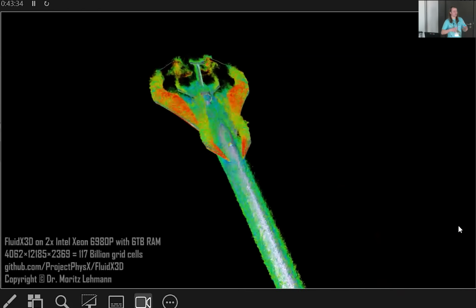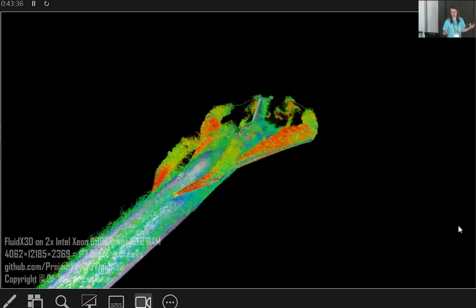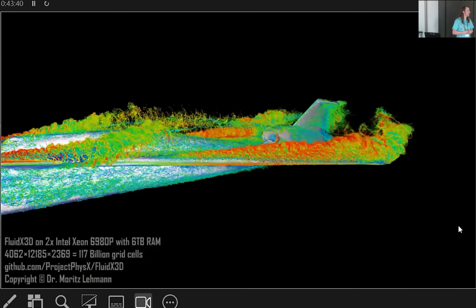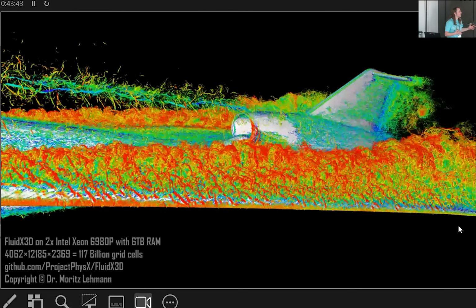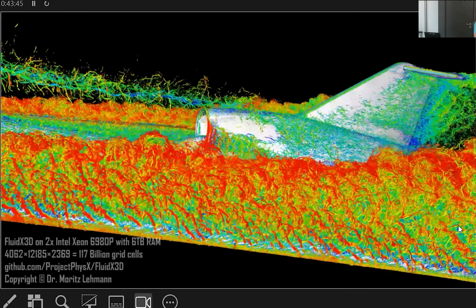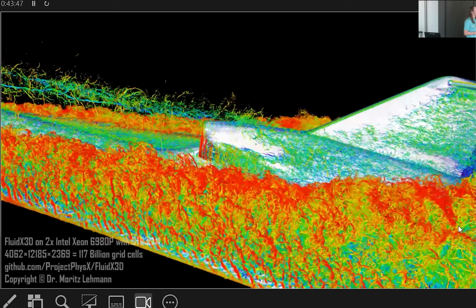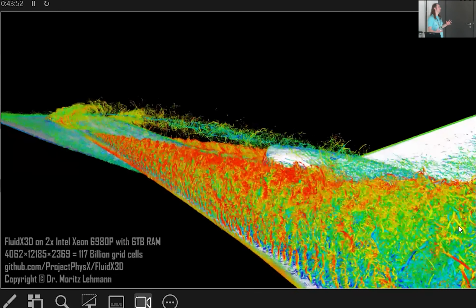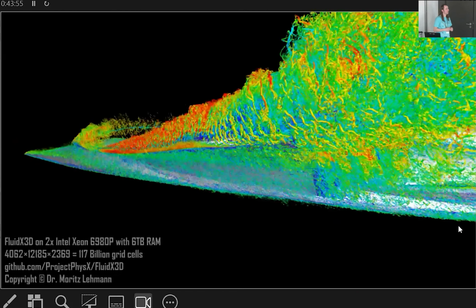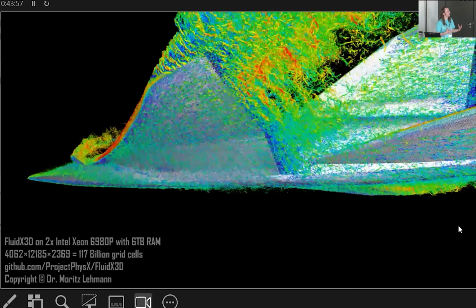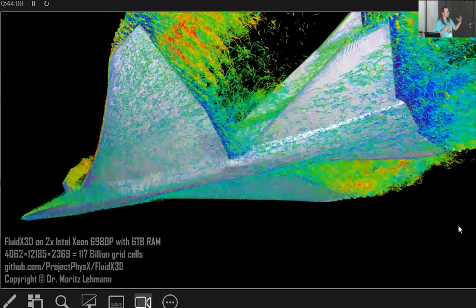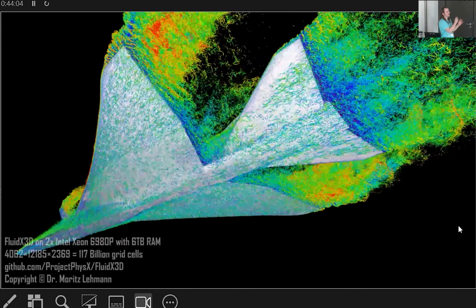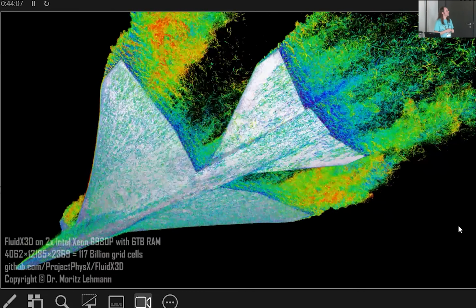And that would be very expensive for hard drive space. It would also blow up the runtime by like 100x because then the bottleneck to the hard drive would slow it down so much. And in situ rendering is the only way to even visualize so much data. Because I wrote the rendering engine in OpenCL itself with direct connection to the raw buffers in the fast GPU memory already, I can just make the GPU simulate a few time steps, then pause, and then render the data to an image, and then send the image to the hard drive.